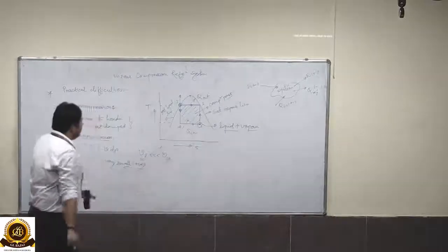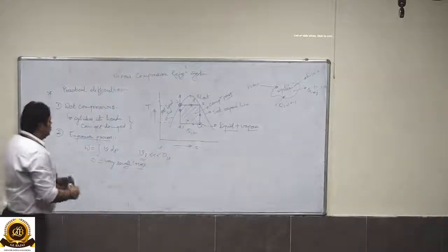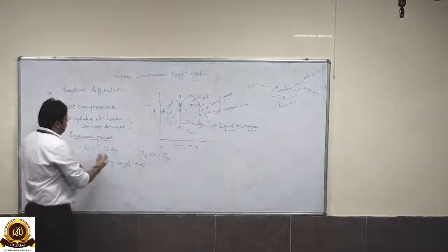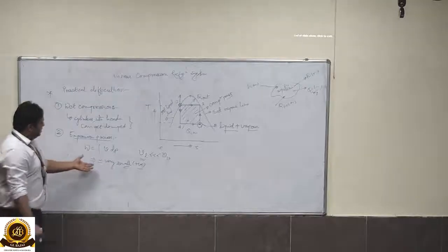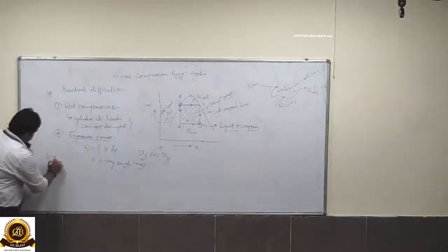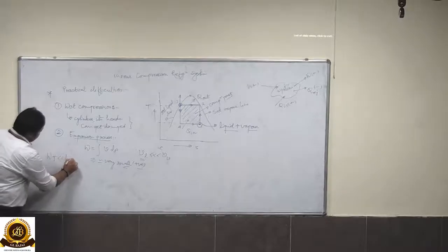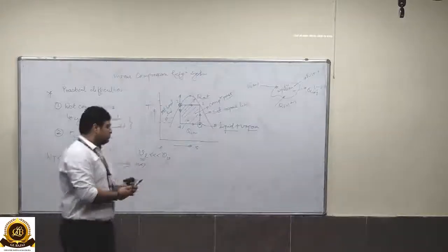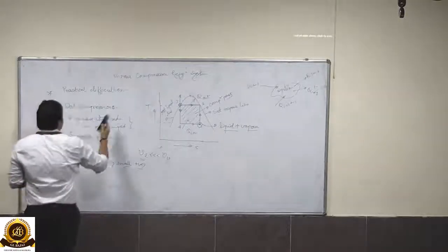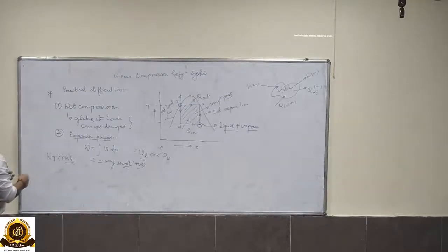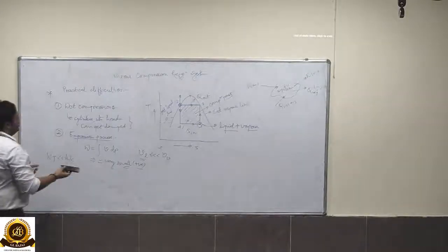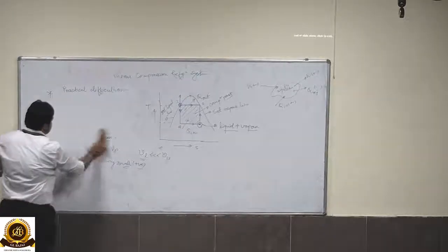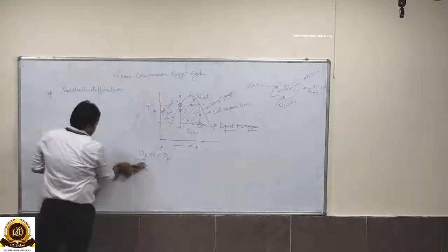So it is not justified to use a turbine for the expansion process, which obviously produces a positive work, but this work of the turbine is very less in comparison to the work being consumed or given as input to the compressor part. So these are the two practical difficulties which we face during the reverse Carnot cycle. That's why it is used as an ideal cycle, and it is used for comparison purposes with other vapor compression or vapor absorption cycles.